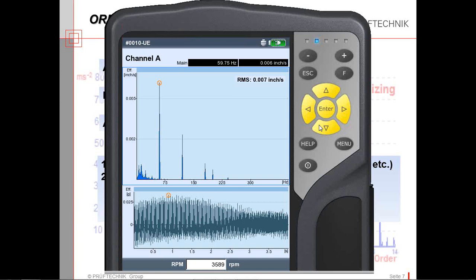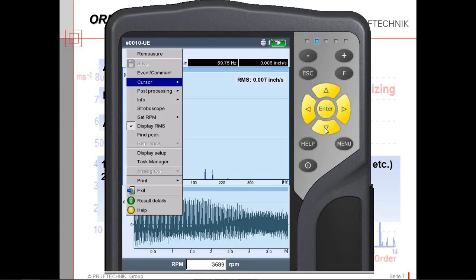But in the whole process of FFT analysis, we use something known as a window. We won't get into that this morning or this afternoon. It's another topic for another day. But the windowing creates something less than an exactly desirable result. So what we have is a routine, a small program that allows us to actually find the peak.